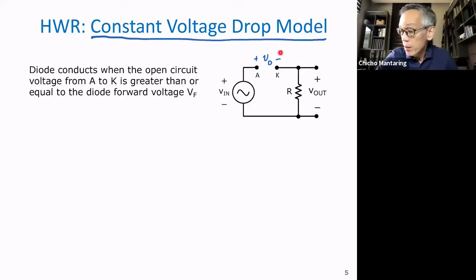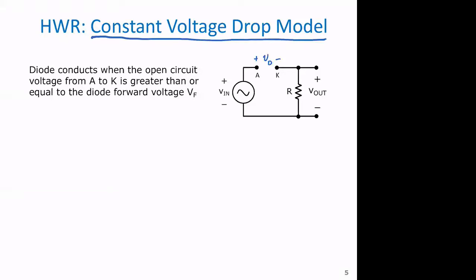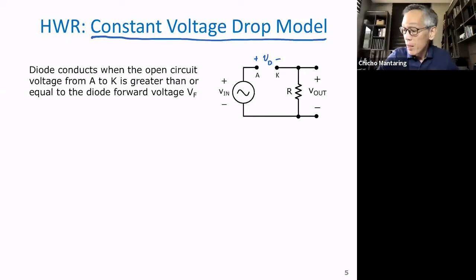Open circuit to? Anyone? V in po, sir? Yes, that's right. No? The value is V in. Why? Your current is equal to 0, and therefore, there is no voltage drop across your resistor. No? So kung mag-KVL ako dito, I'm going to get V sub D plus 0 minus V sub in is equal to 0, or V sub D is equal to V in.